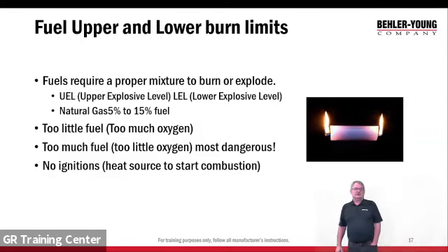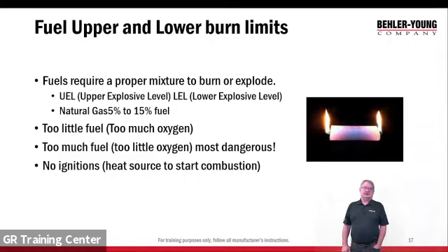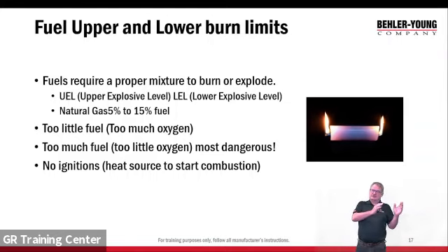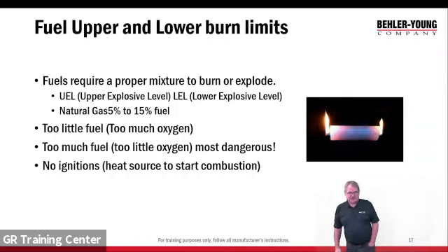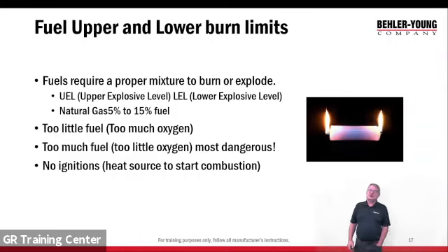So fuel requires a proper mixture to burn or explode. Okay, so the upper explosive level and the lower explosive level. The upper is if I have more than this, it won't ignite, and lower is if I have less than this, it won't ignite. So here it says natural gas has a lower explosive level of 5%.